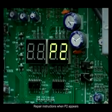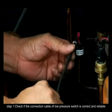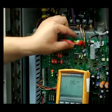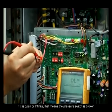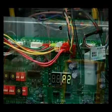Repair instructions when P2 appears. Step 1. Check if the connection cable of low pressure switch is correct and reliable. If it is normal, use the OHM range of multimeter to check the resistance. If it is open or infinite, that means the pressure switch is broken.